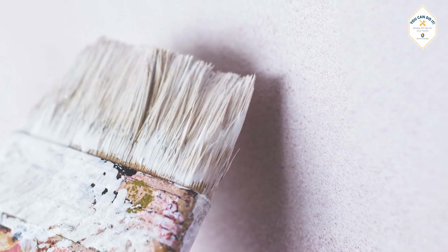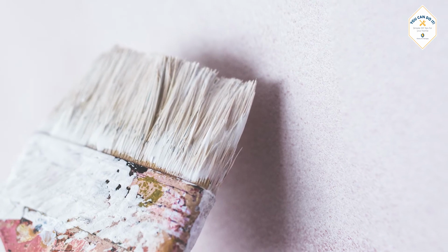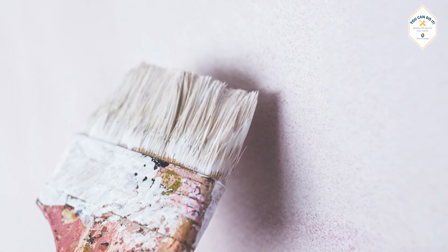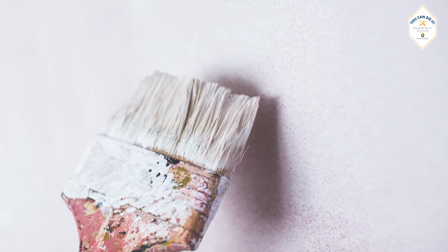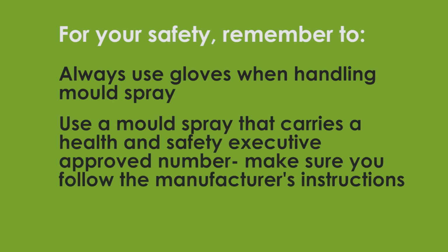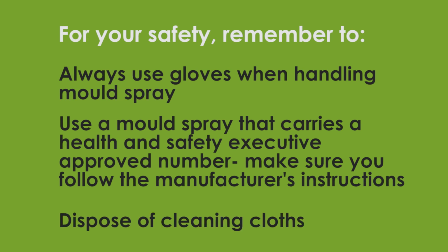After treatment of the affected areas, redecorate if needed using good quality fungicidal paint. This can be found at most supermarkets and hardware stores. For your safety, remember to always use gloves when handling mould spray. Use a mould spray that carries a Health and Safety Executive approved number. Make sure you follow the manufacturer's instructions. Dispose of cleaning cloths.